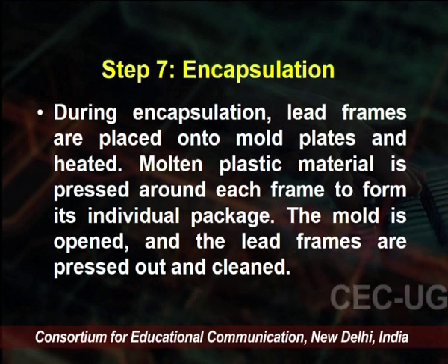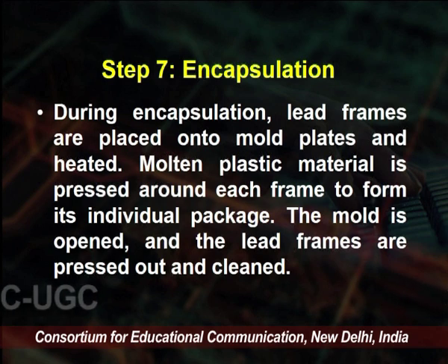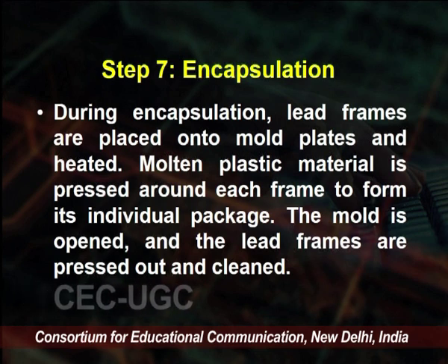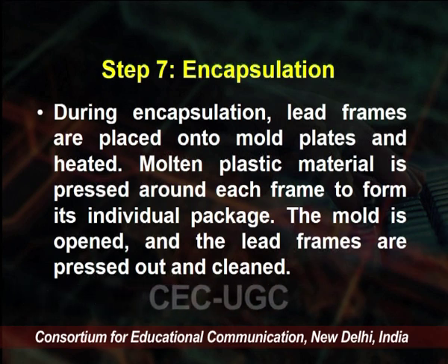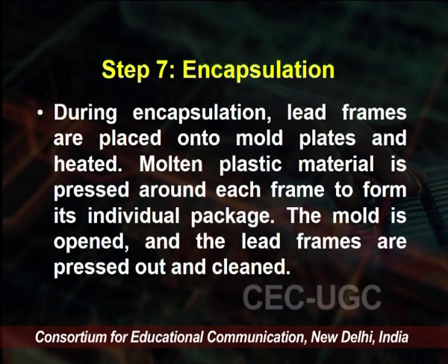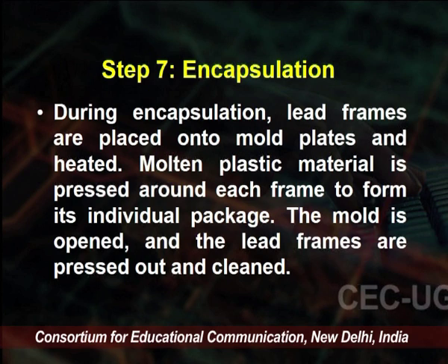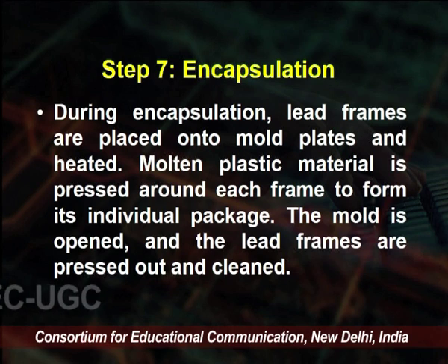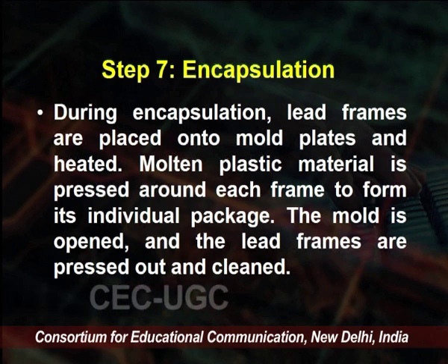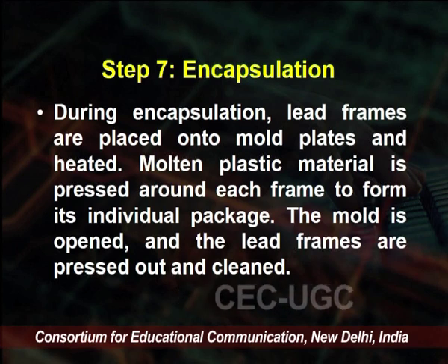During encapsulation, lead frames are placed into the mold plates and heated. Molten plastic material is pressed around each frame to form its individual package. The mold is opened and the lead frames are pressed out and cleaned.